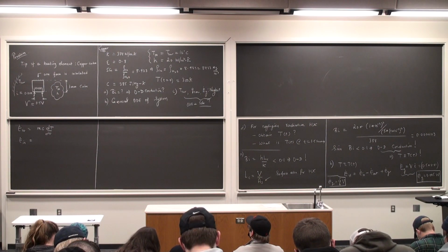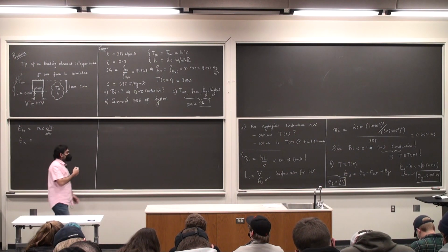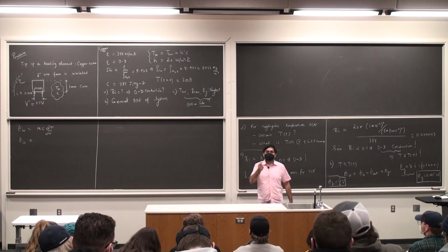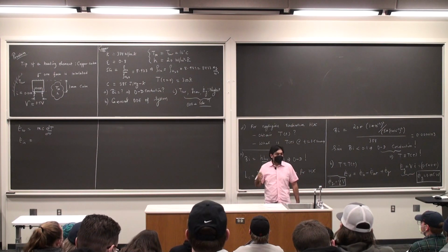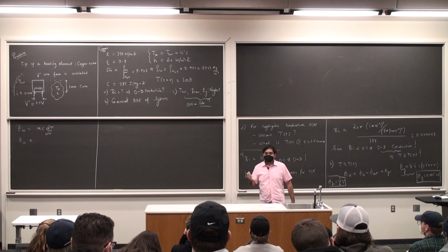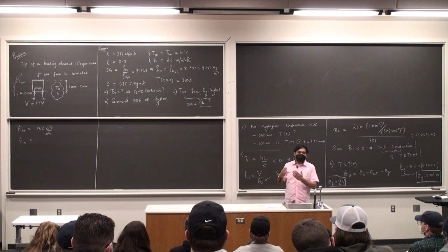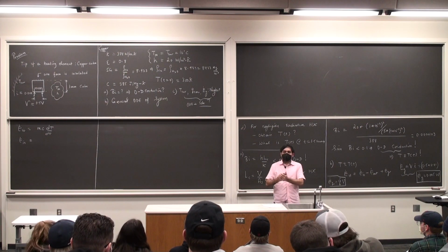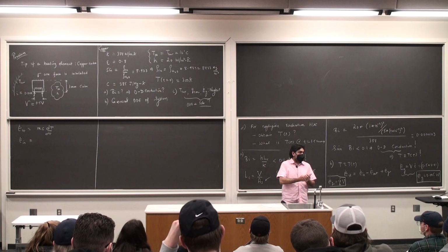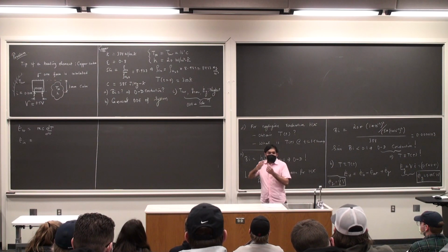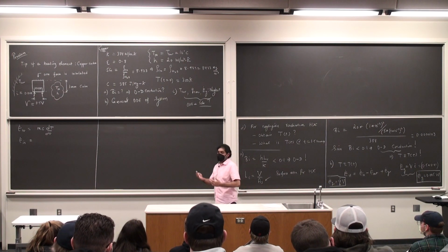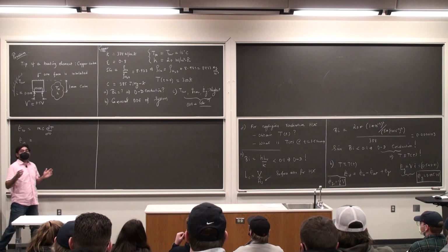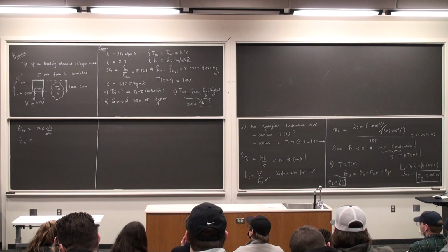This is where you make a judgment call, and you immediately recognize that the initial temperature of this cubic element is greater than the ambient temperature, the surrounding temperature, which means that there is going to be some heat loss from the cubic element onto the ambient in the form of convection and in the form of radiation. Right? There is going to be a certain amount of energy emitted by this cube. But at the same time, there is also irradiation on the cube from the surroundings. That's going to be the energy that's coming into the cube.